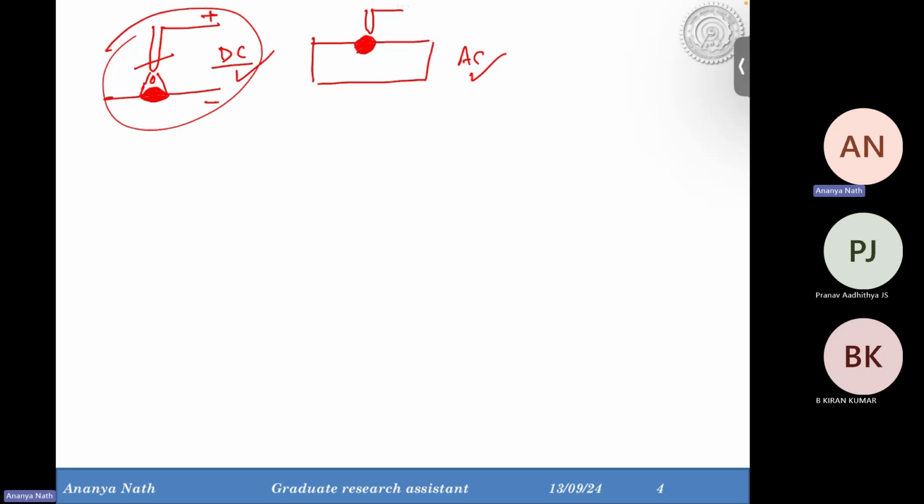That means if you are not providing sufficient argon gas, everything will be oxidized there. So aluminium is a very tricky material to work with in additive manufacturing. That's why people do not generally use aluminium. But I know it's very difficult to work with, because my PhD is on aluminium.